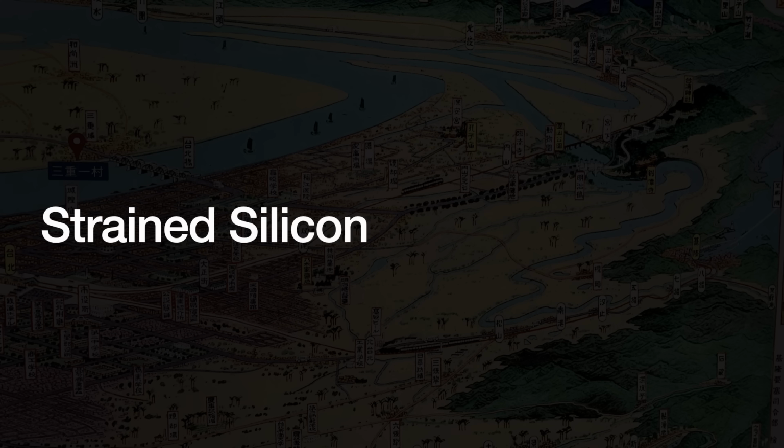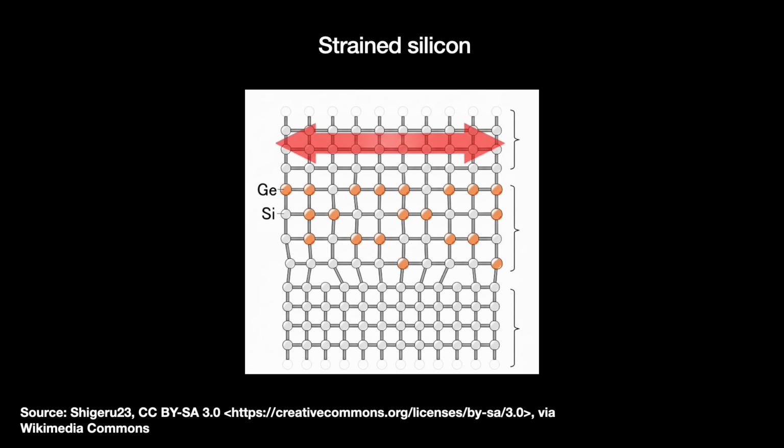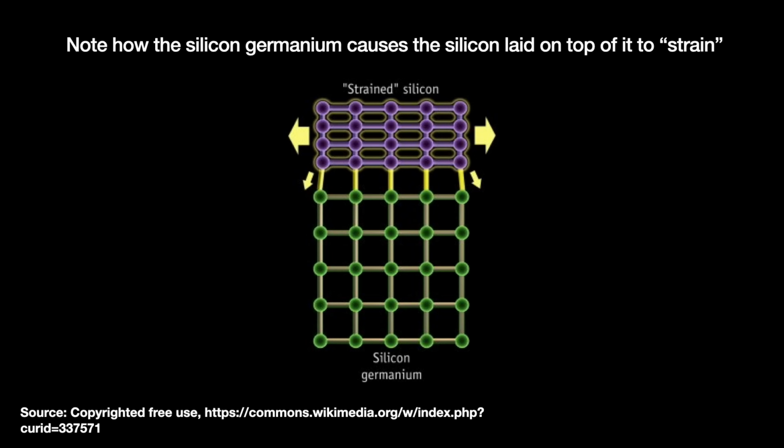Earlier, I made a brief mention of strained silicon, and you might have thought that was it, wasn't it? No way. Strained silicon refers to layers of silicon where the silicon atoms have been stretched a bit further beyond what they are normally used to, like cotton fabric pulled apart. Strain changes the silicon's atomic structure. Charge carriers can travel faster and experience fewer obstacles, quote-unquote, i.e. scattering, through strained silicon than relaxed silicon. So you get a 35% speed or 25% power consumption boost without needing to shrink the transistor.